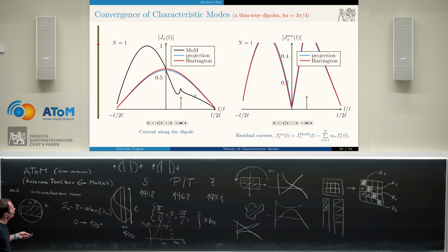And at frequencies where these two modes are modally significant, we can probably realize, with these modes, a Q which will be very close to the overall Q. And look, the first mode is resonating here, so it's extremely significant there, and it's perfectly compatible with the feeding in the middle. And you can see that the black line is closely following the line of the Q factor of the first mode. And then at a region where the first mode